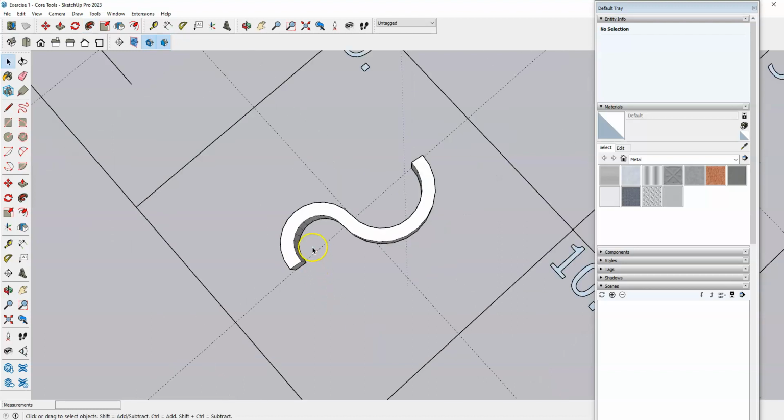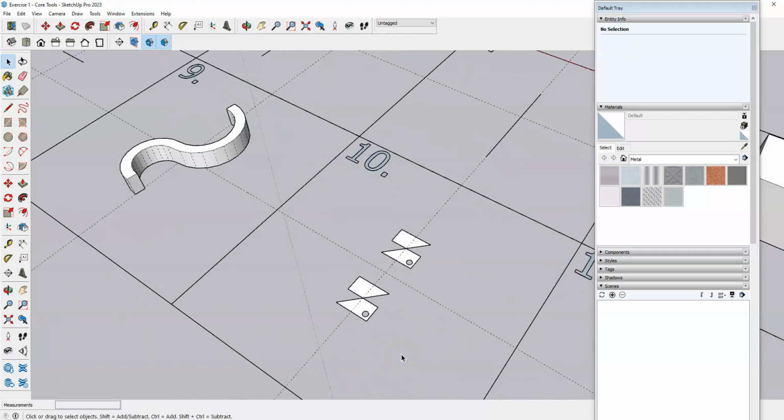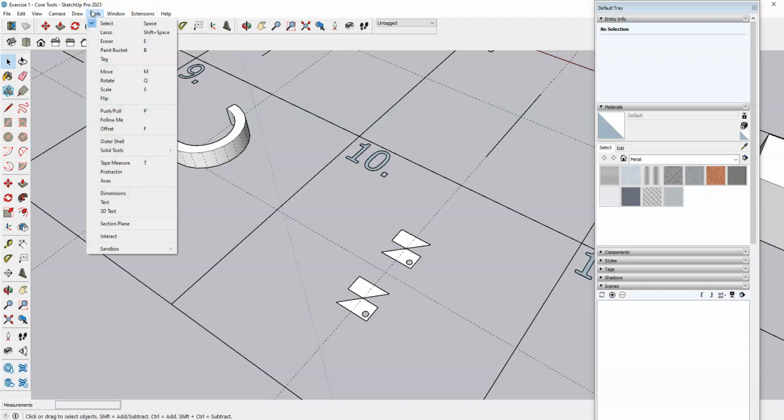All right, box 10. This one we're going to learn the flip tool, or mirroring an object. So this flip tool is actually new with 2023. So if you're ever working in a version that is before 2023, you used to just right-click an object and hit mirror. But now we actually have a graphic tool for it. So if it's up here in your ribbon, if not, we can still go to that Tools drop down and find Flip there.